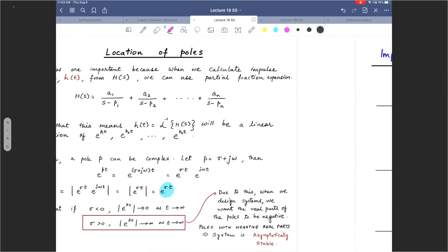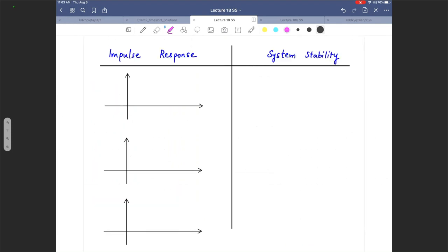Now let's talk about the location of zeros. With respect to stability, the location of the zeros is not at all relevant. It's the poles that dictate unstable behavior, because things becoming zero are finite. They belong to the region of convergence. That's good, it's not unstable behavior.